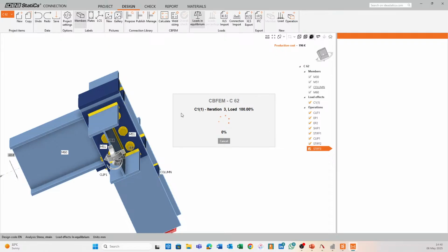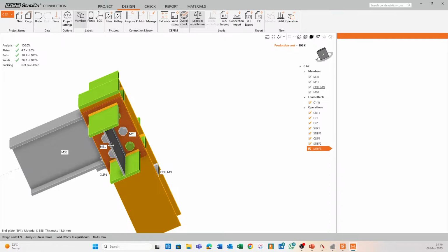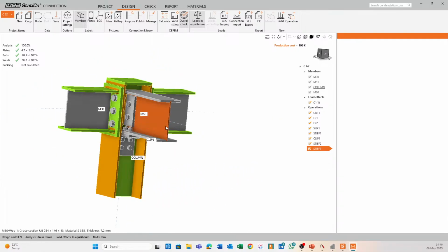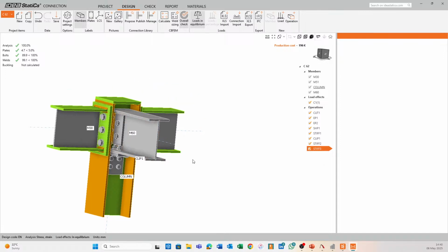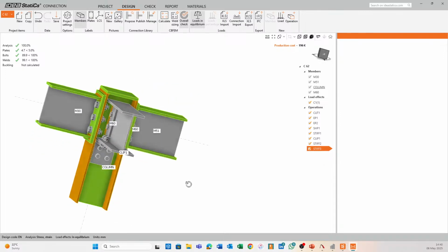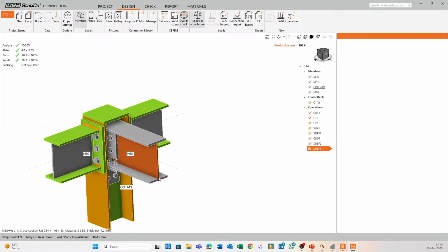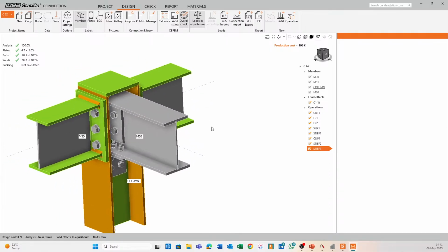But I hope that this principle is now clear, that for you as an engineer, you can actually see how stiffening up different parts of the model will take loads or stresses away from other parts, which makes sense. Because usually what we work with is we're actually working with stiffnesses, right? We're trying to make different parts stiffer so that they pull more of the loads towards themselves.